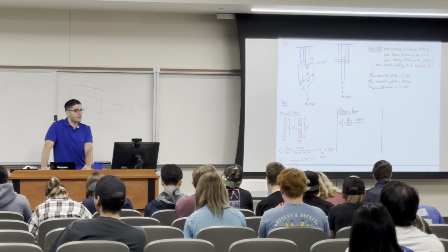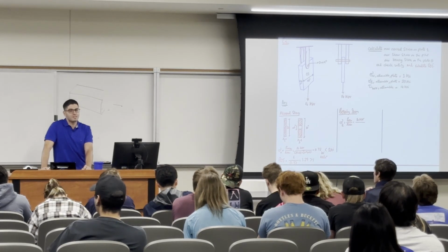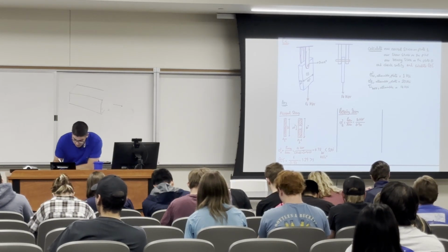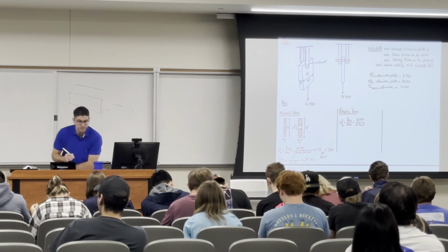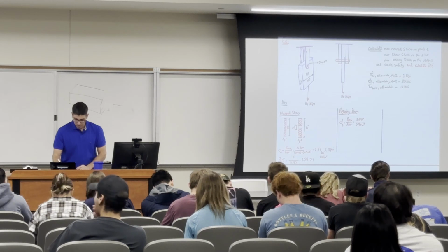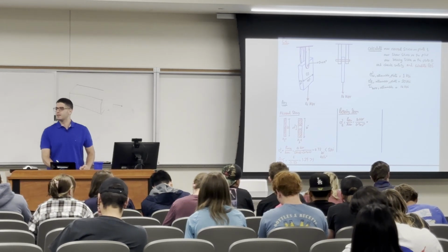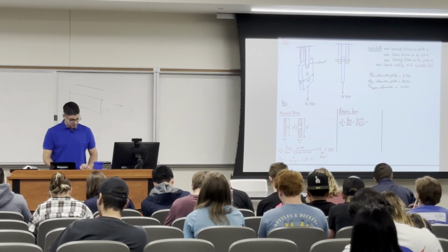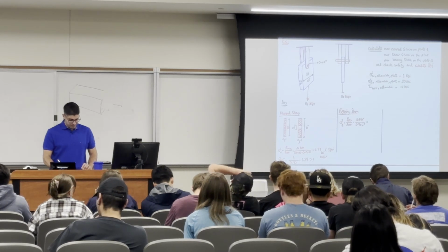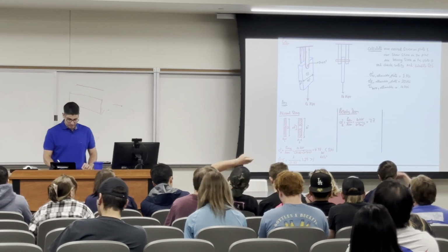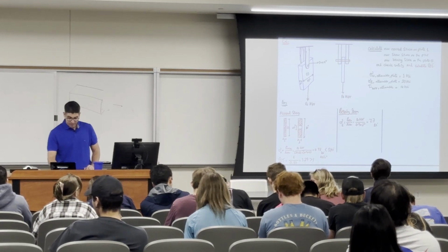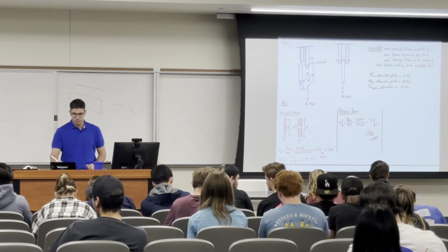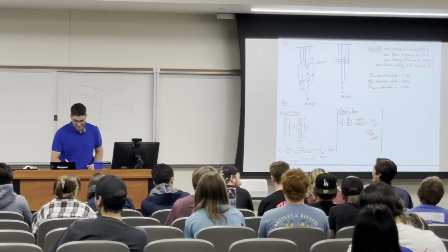0.9 times thickness. Do I get a second on that? Anyone disagrees with that? Okay, so the area here is going to be 0.9 times the thickness, which is what? 2 inches. Okay? What is the stress here? I'm getting 7.7 KSI. Am I safe or unsafe? Yes. I'm safe. So you can write safe. And you can do your own signature. I used to do this when I was a student. I used to make it like this, as if I designed this.